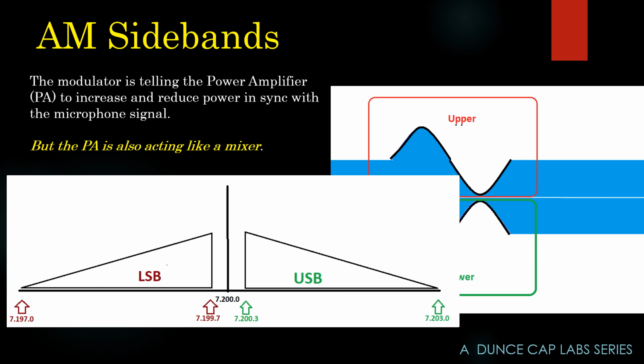So the human voice might just modulate at something like this. Now, the reason there's a slope to those triangles is the farther out you get, the higher frequencies of our voice generally don't convey a whole lot of power or information unless you use a lot of audio processing. So this slope isn't really real. It doesn't necessarily apply. It's theoretical, but it's one thing in theory that doesn't really work out. If you use a high fidelity audio mixer between your microphone and your radio that emphasizes the higher frequencies up toward 3000 hertz, the slope won't look like this at all. And that's okay. That's fine.